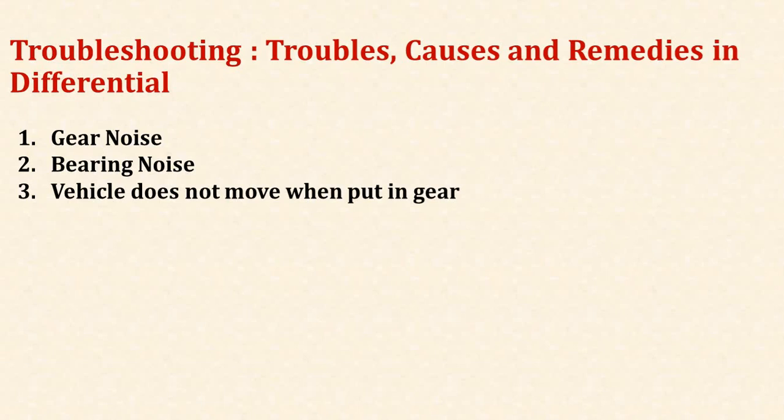Then in gear noise, another cause is low viscosity, poor quality oil. So what remedies do we have to take? We have to replace it with the correct quality of gear oil. Then the next trouble encountered during gear noise is wrong adjustment of the drive pinion and ring gear.